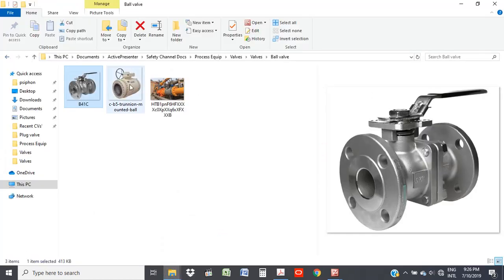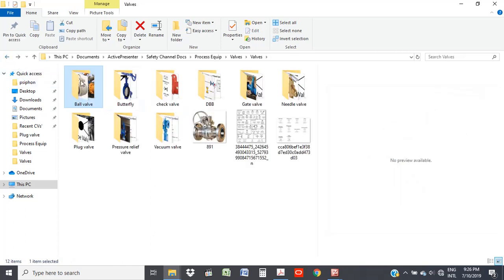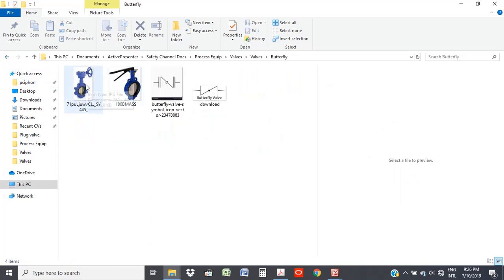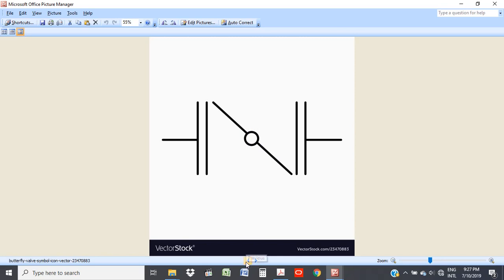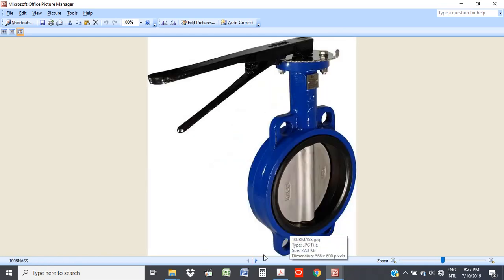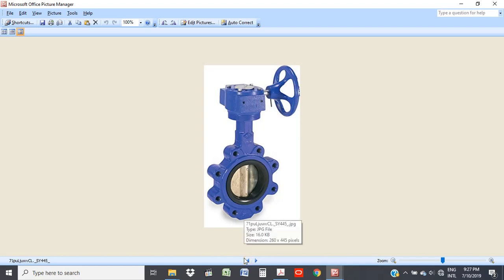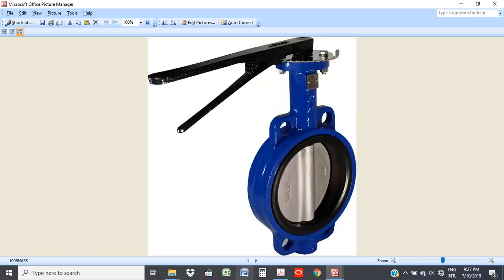Then the next we'll be looking at is a butterfly valve. Now, a butterfly valve, this is what it looks like in real life. When you see it in a facility, this part will be part of the piping. So what you would see is this and the rotating lever. You might not be able to immediately identify it if you're kind of new in the oil and gas. So it could have this wheel to control this, and it could have just a lever that you turn.